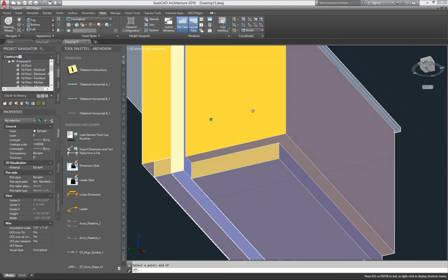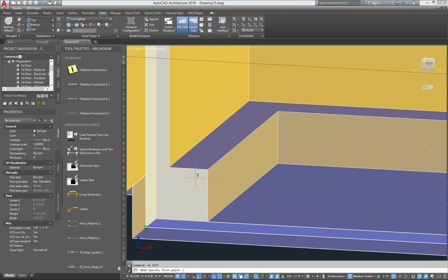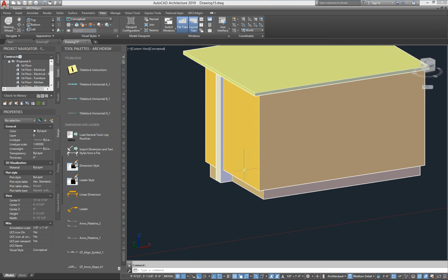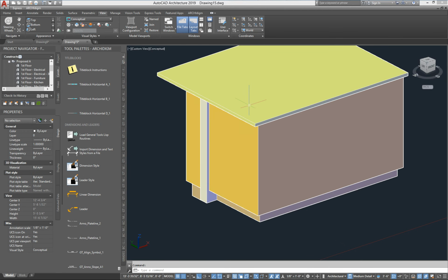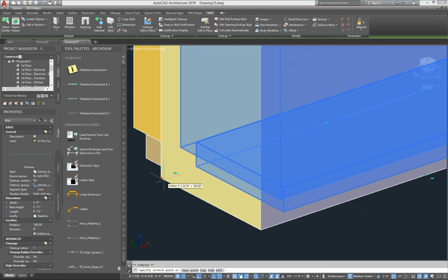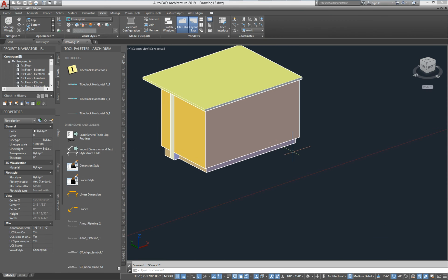Let's see what happened here. Let's check that dimension. That's good, that's 3 inches. So we lost an inch because it is trying to compensate for the 1 inch of overhang if it had a countertop. So all you have to do to fix that is just pull it out 1. Now, if that's confusing, we'll just build an end cap for the second counter.